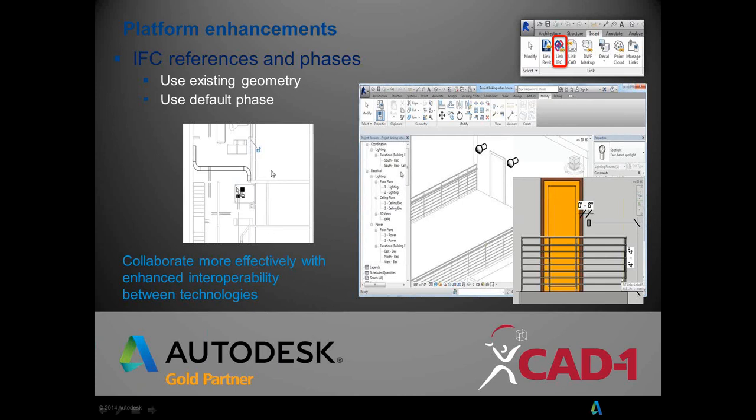And so the IFC references: when you have an Industry Foundation Class file referenced into your project, before you were not able to host a lot of objects to it. And so they have improved that. You could still host some objects, some of the face-based objects that you find, or if you have created, you can now host those on IFC geometry.